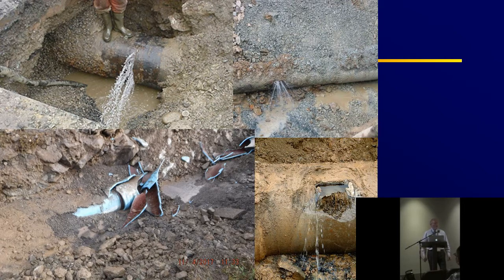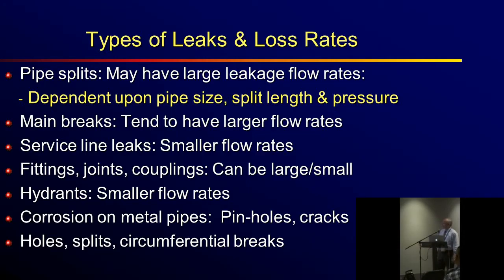Now, these will be surfacing leaks. They won't be very hard to find because both of these leaks at the bottom took out several hundred meters of road. It just goes with high pressure. The other ones, these didn't surface, and they can run for a long time. And my argument will be some of them have been running for years. Very high flow rates, very high volumes of water that are lost.